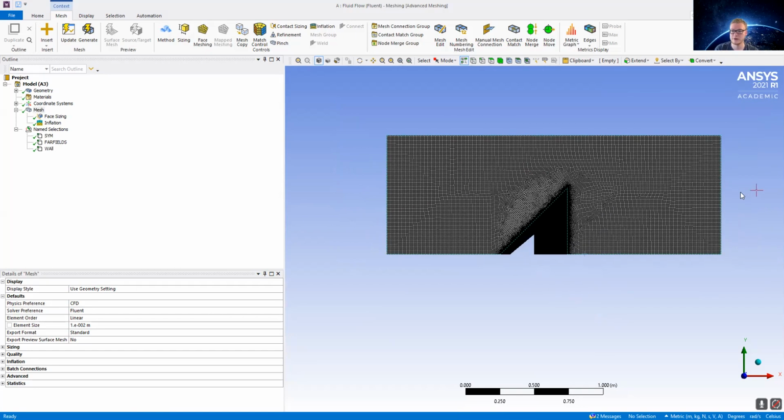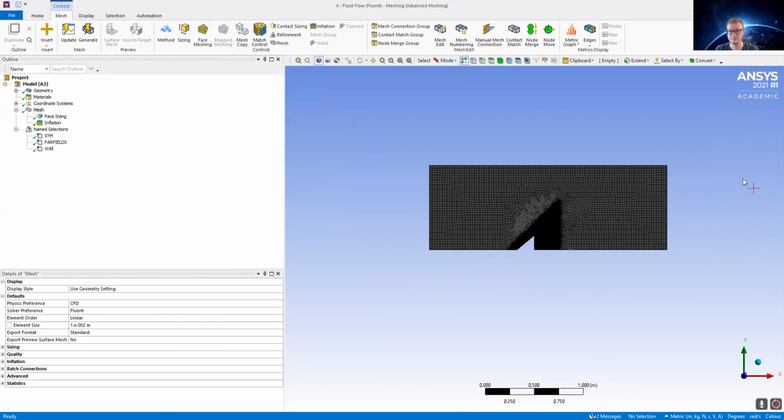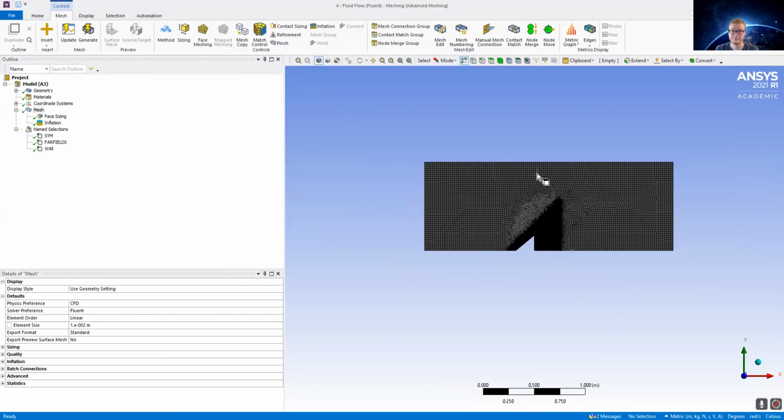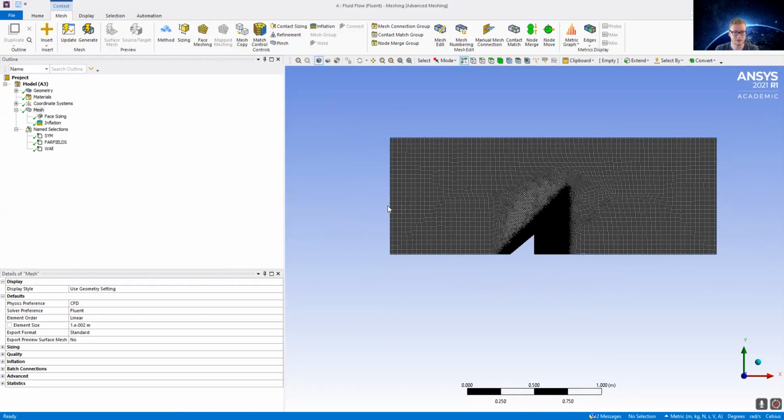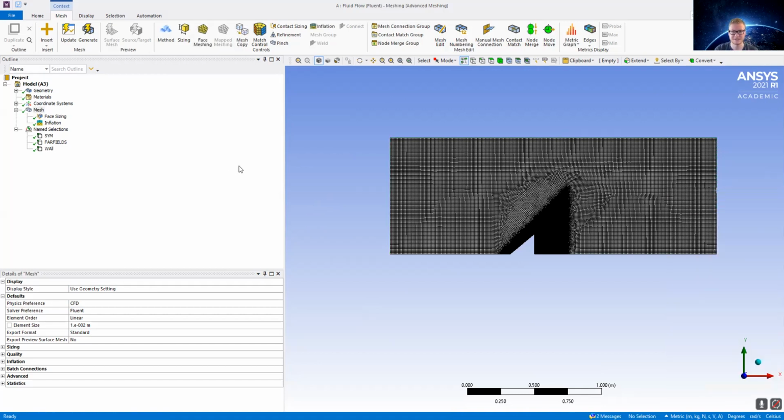And next, you're going to want to create your far field condition. This will just be a calculation where it's taking a Mach 3 airspeed throughout the whole testing chamber, which is about this entire rectangle. You can make it a little bit bigger. It'll probably make it a little bit more accurate, but this is what I went with. So you're going to select it just like the other one. Right click and click create named section. Call it far field. It's going to show up as a wall. Don't leave it as a wall. I'll show you how to switch in a minute once you get to the testing section.